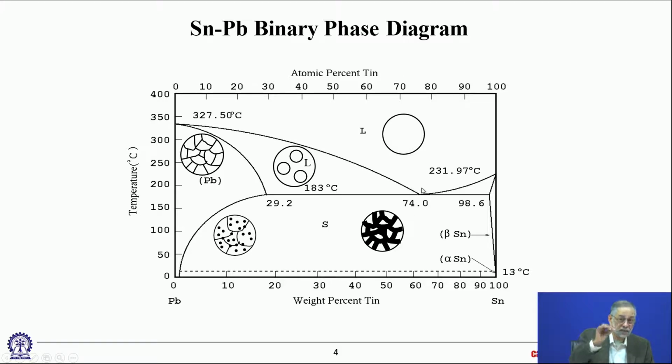Right, so low pasty range. If I cool from here, it starts converting from liquid into solid over here and does not fully solidify until here. So there's a big temperature band over there during which it's still in the pasty region and dangerous because components can shift around, right? So second reason, that's one. Excellent. Give me a second reason why I would rather have a solder here than a solder here.